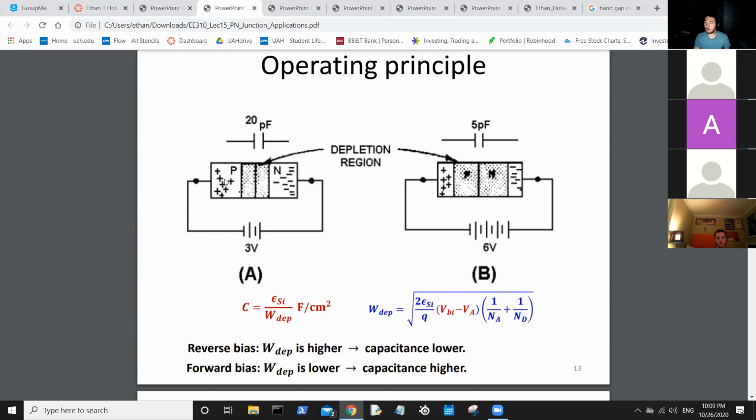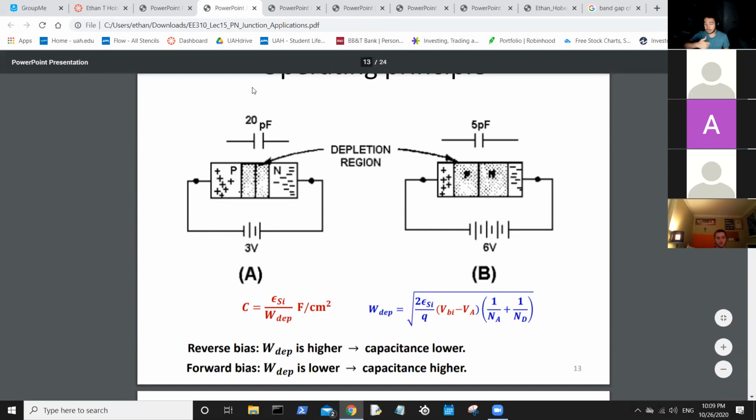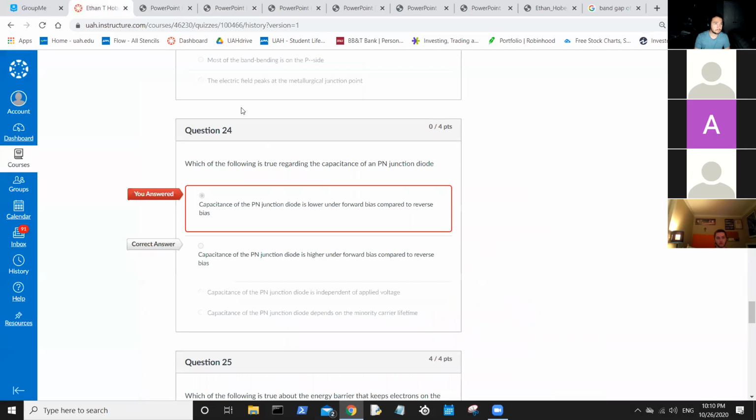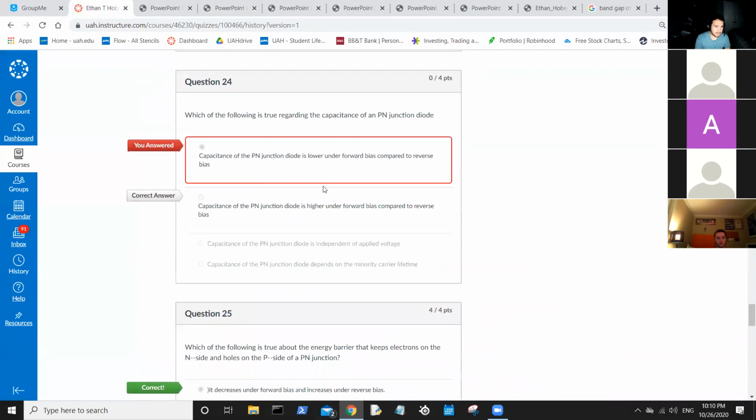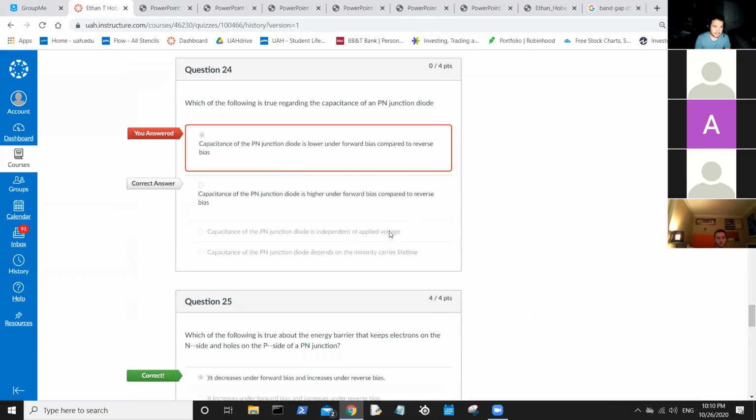Therefore, forward bias is the proper method to increase the capacitance by decreasing the depletion region. Reverse biasing it is going to cause the capacitance to drop because the plates, per se, the edges of the depletion region, will move farther away. Forward bias moves them closer together. That's how you answer that question. And that's the formula we'll write down later. We're getting there. So that's why that's that. Cool. That did not take long.